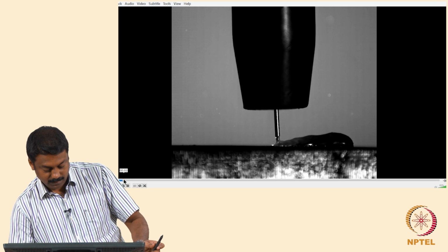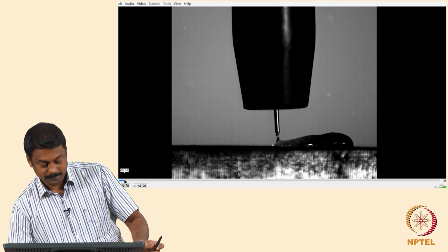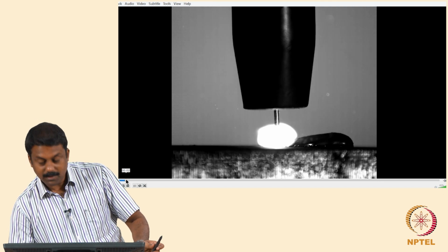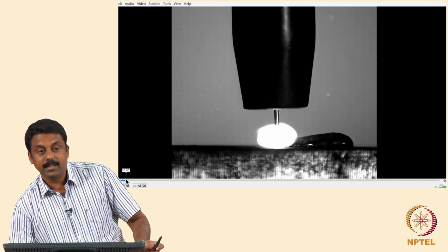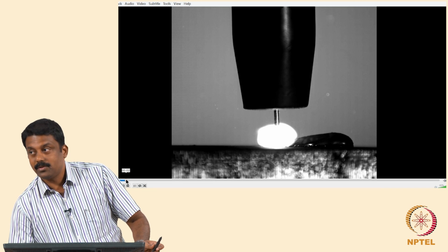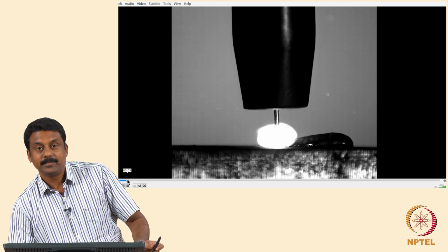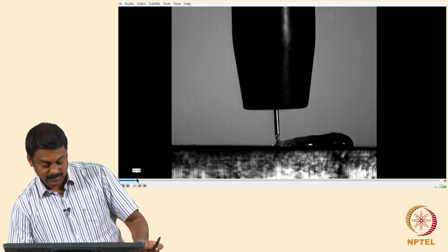So it goes back and the droplet is transferred. You see that? And then the moment a critical length is achieved, the arc is struck, ignited by the high frequency ignition, and this process continues. Yes, so you keep on doing it.